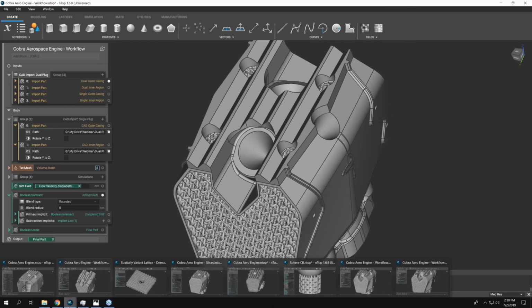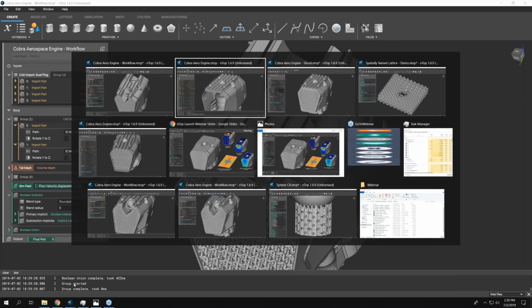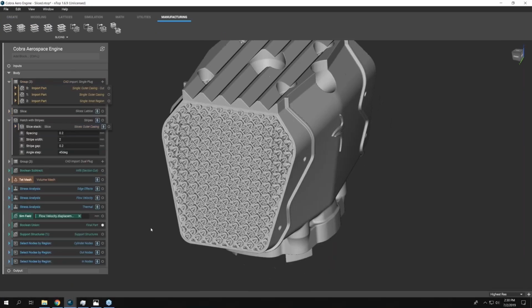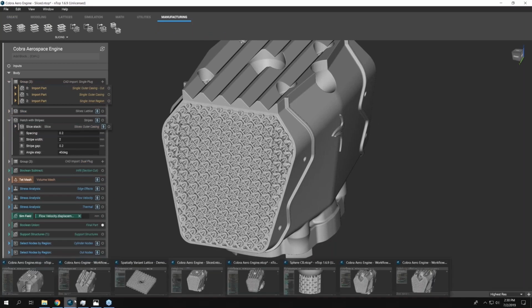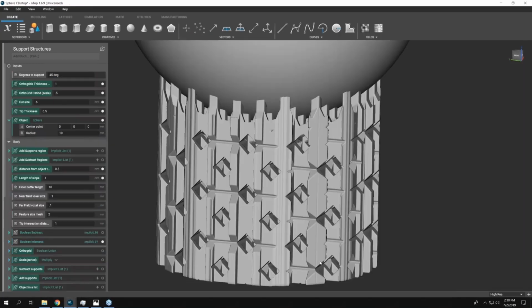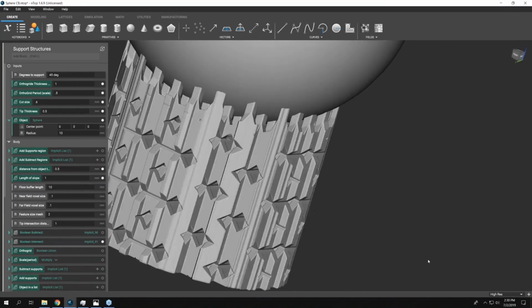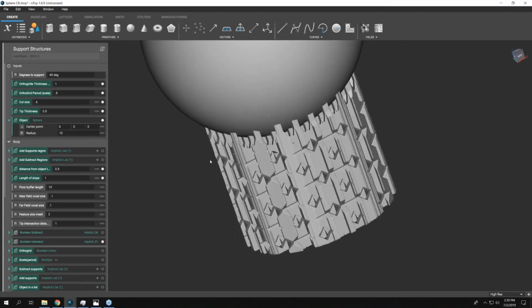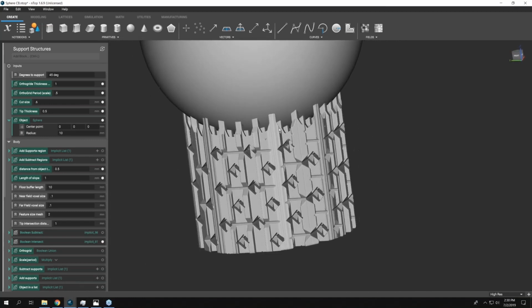Now, one thing I would like to touch on again, which I skipped over, was that a lot of times, I know we had a few manufacturing engineers in the audience. A lot of times we have people develop very specific support structures for their additive manufacturing workflow. And in this case, it's no different. So we had our manufacturing engineer, Chase, he designed these support structures specifically for the material and machine that was being used and tested them on a variety of coupons. And you can see the detail of the teeth and the reliefs here.